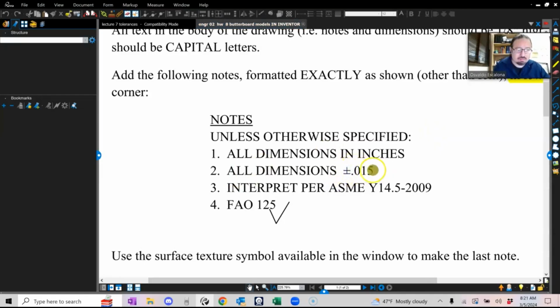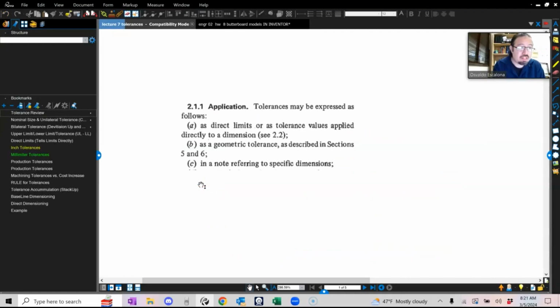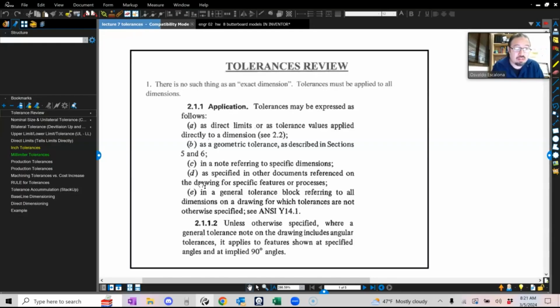So this is the leeway, the one that I was telling you guys about. And again, there should always be a leeway because in the drawings that you make, nothing will be perfect. The tolerance is pretty much telling your manufacturing personnel what the upper limit and the lower limit are that they can fabricate the part to. It also controls the form of the part.